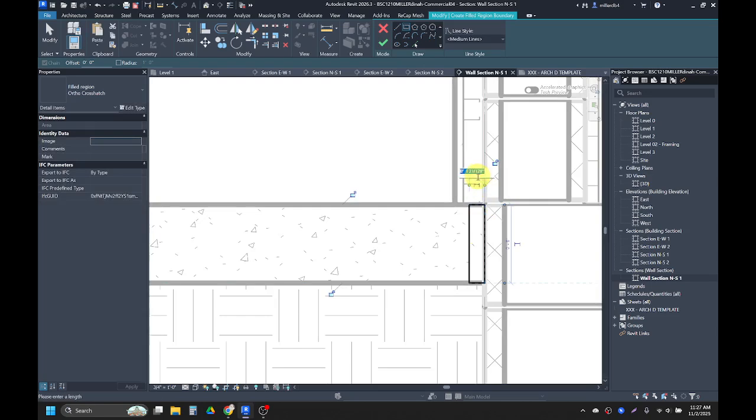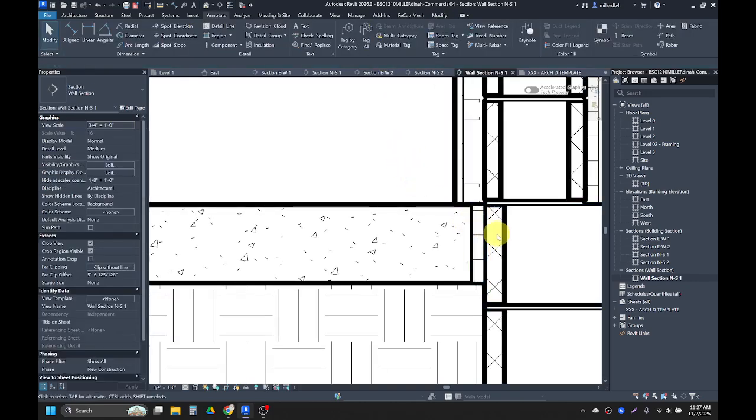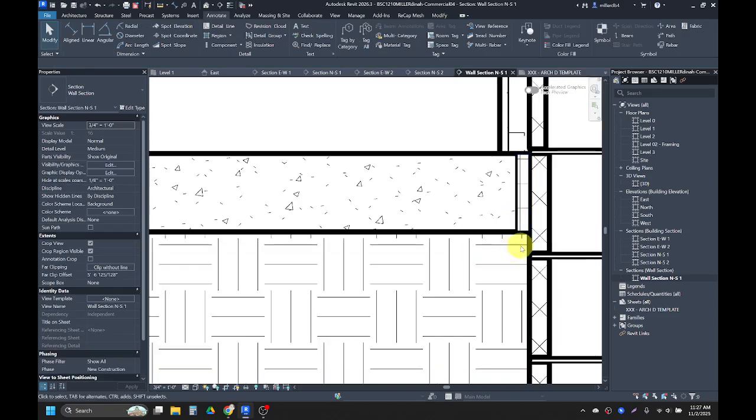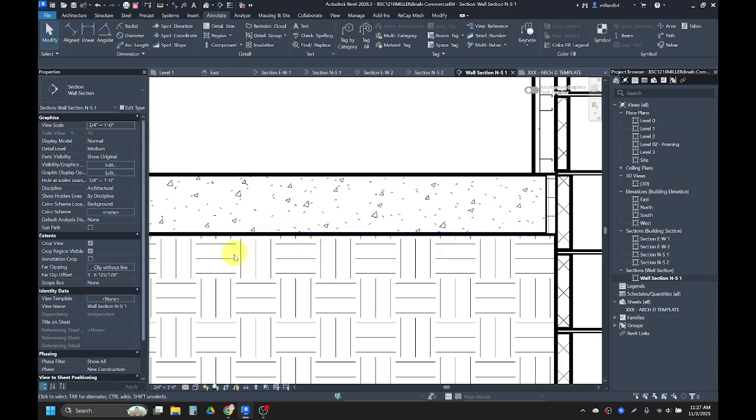And then I'm going to click on this number here and change this to just 1 inch. That's 1 foot. 0 space 1. Enter. And then I'll click OK or my green check. And what I've done is just made a new little area that has a different hatch pattern there. I'm going to do another one for a layer of 2-inch rigid insulation that's sitting underneath here.